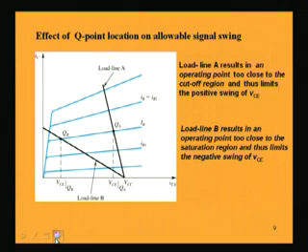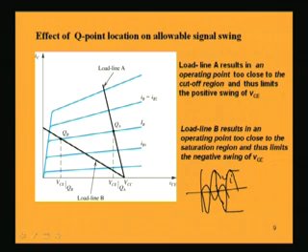I want to get as large a swing as possible in the output. Suppose I give an input signal, a very small weak signal, I expect that my output signal at the collector should have a very huge swing, meaning the peak to peak values must be as wide as possible, while the swing must also be distortionless. I should not get a clipped output voltage.